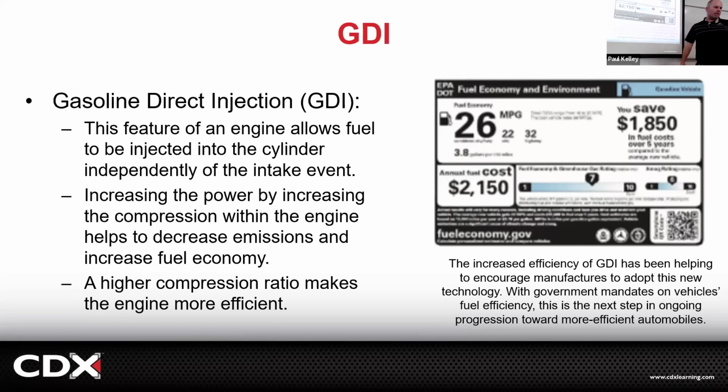But a big part of it's GDI, right? So we're getting big numbers. We can do a couple cool things. It's injected directly into the cylinder, separate of the intake event, which will increase the power. We can also run higher compression, and generally we do. That's better for fuel economy and emissions.